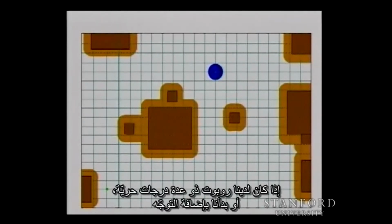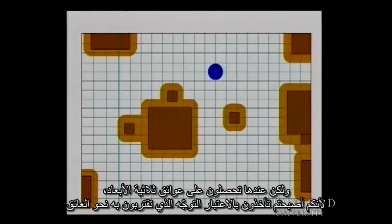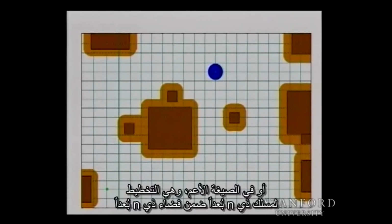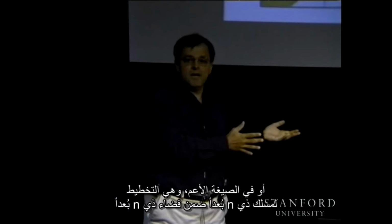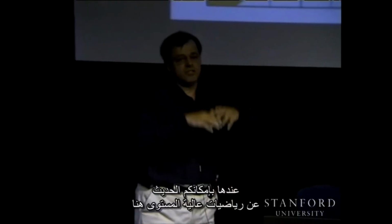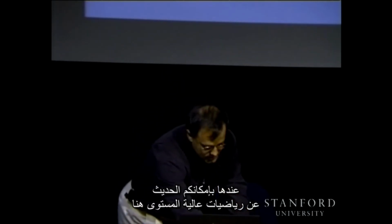If we have a several degrees of freedom robot, or we start adding orientation, then these configuration space obstacles can be not only planar, which is what we have here, but three-dimensional, because you're thinking about the orientation that you're approaching with. Or you can get many-dimensional obstacles if you have many degrees of freedom. So in its more generic form, that becomes planning for an n-dimensional path in an n-dimensional space. Then you can start talking about kind of high math there.